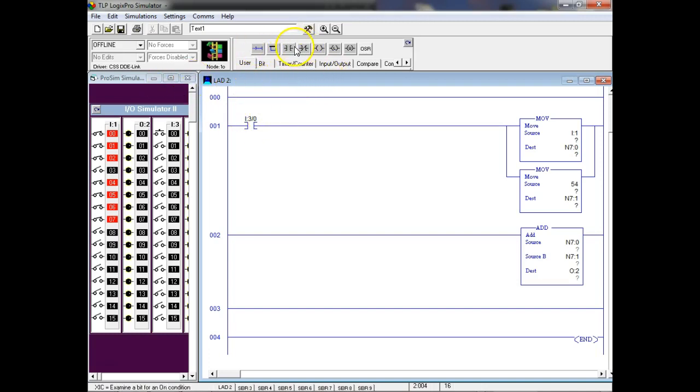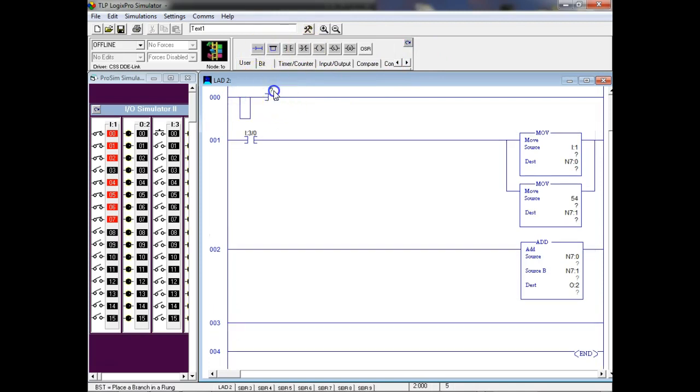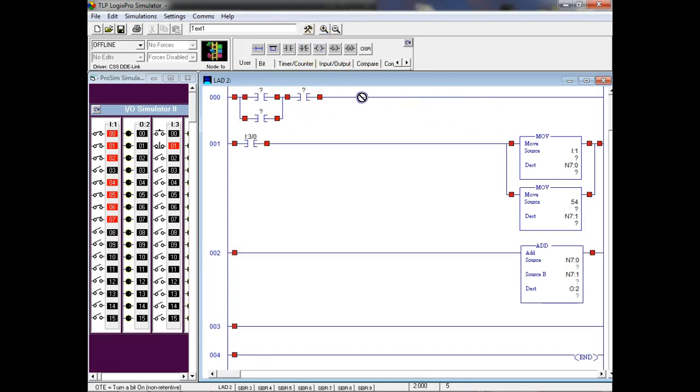So what's our master start/stop? We'll come up here and put a start, and then put a drop down, right? We'll do it the way they do it in Germany, where they put the stop over here, and it's going to be true if it's closed. So I'll make my stop button normally closed, so it's already true, right? And then we'll put a seal-in, and then over here we'll use one of our internal bit files. I'll call it input.